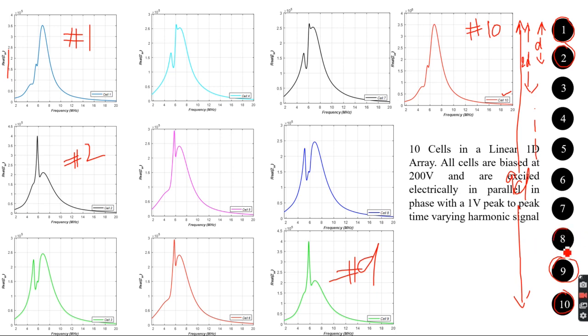Okay. Likewise, number 8 is going to experience the same effect of crosstalk as cell number 3. This is cell number 3, and let's see where cell number 8 is. Yeah, this is cell number 8, and you can see the same bandwidth, the same impedance level, the same sort of spurious resonance, a bifurcated sort of resonance you can see over here. It's very similar because of reciprocity. So then again, if you go for cell number 4, this is cell number 4, and cell number 4 is going to be the same as cell number 7. So yeah, here's cell number 7.